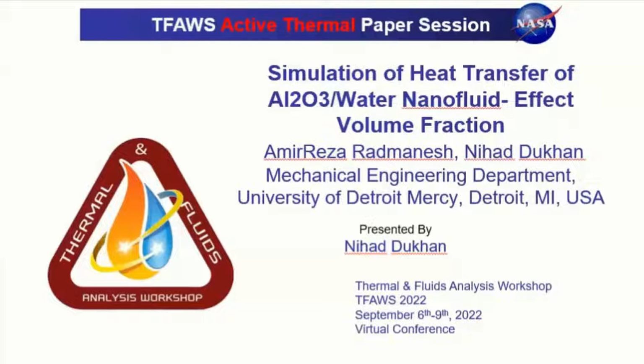When we do that with nanoparticles, we actually get also an increase in the heat transfer coefficient for forced convection. So the issue is not only increasing the thermal conductivity, but researchers have noticed an increase in the convective heat transfer coefficient as well.